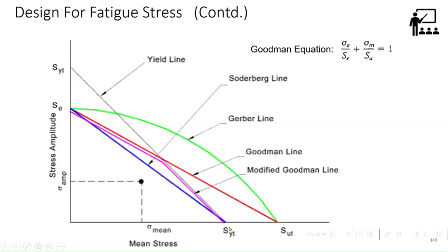So sometimes that can be replaced with the modified Goodman, where you are changing the numerator. But nobody talks about the modified Goodman equation when you do the mean stress correction factor for the Haigh curve. It's always Goodman, because your mean stress will always be well below this. It is a very conservative side, so that's why they don't worry about the modified Goodman line.